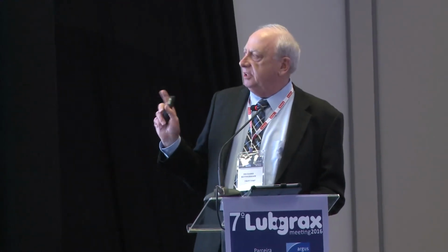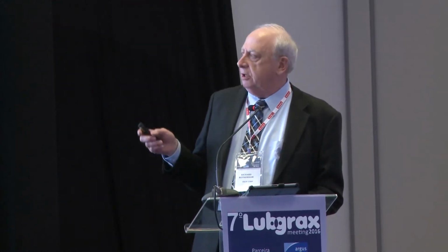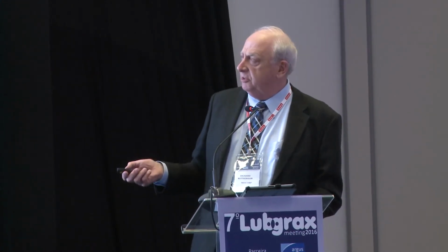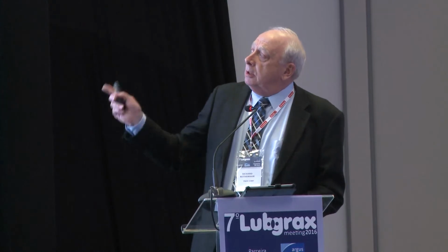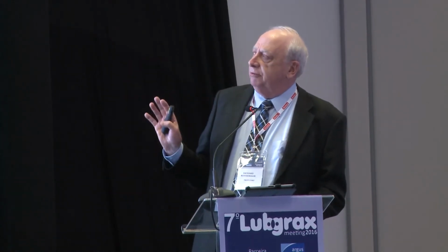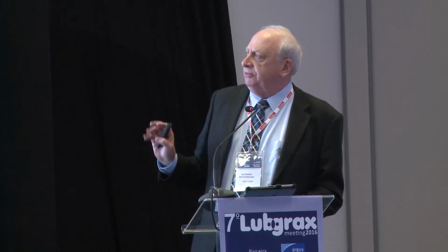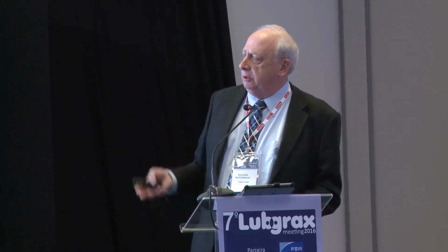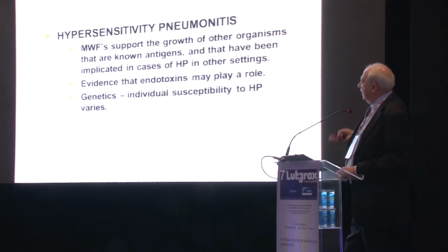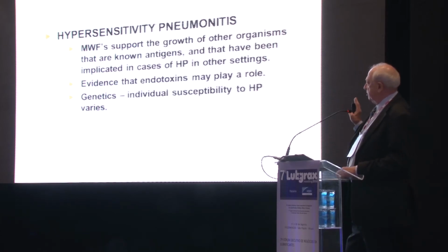So it's very clear that there are other causal agents that are involved in some of these outbreaks. Bottom line is metalworking fluids support the growth of other organisms that are known antigens. So it's not as simple as mycobacteria. There are also animal studies that show that endotoxins may be a cofactor.